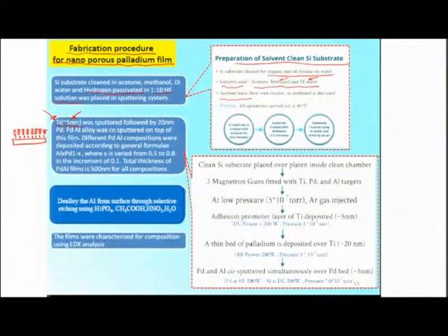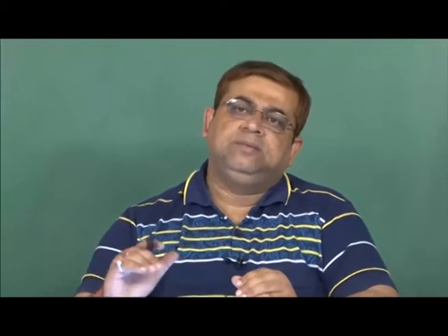So sputter coating is a sort of vaporization process where there is a metal target and a plasma which is generated. The plasma knocks off some of the metal and carries it towards the bias that the plasma system has, and typically the substrates are on the ground plate, where this bias voltage drives the plasma along with the material to the surface.